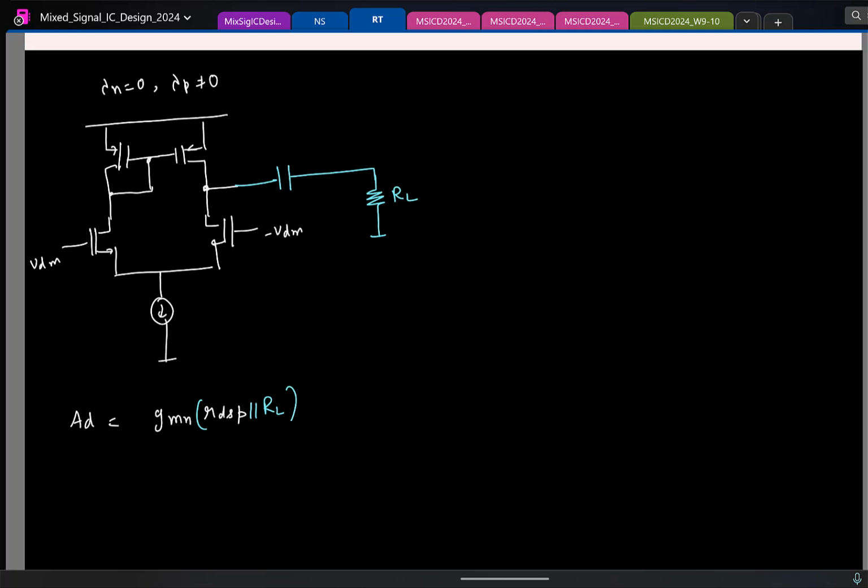Now remember that if I say I want to make an op amp, this is what you want to do. Now an op amp is what kind of a controlled source? Voltage controlled voltage source. So at the output side it is behaving like a voltage source, right? Which means if I connect any load at the output, should the voltage change? It's a voltage source. If you put an elephant across the voltage source, it will maintain that voltage across that elephant. Nothing should change. But here I put a load resistor and suddenly the output completely changes.